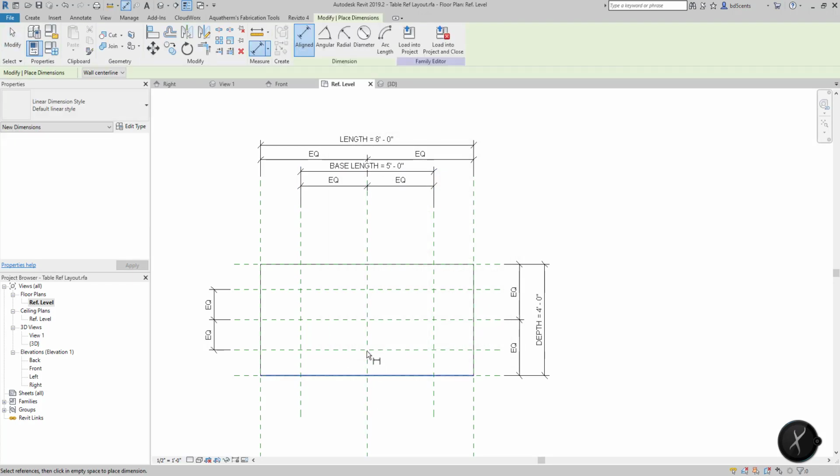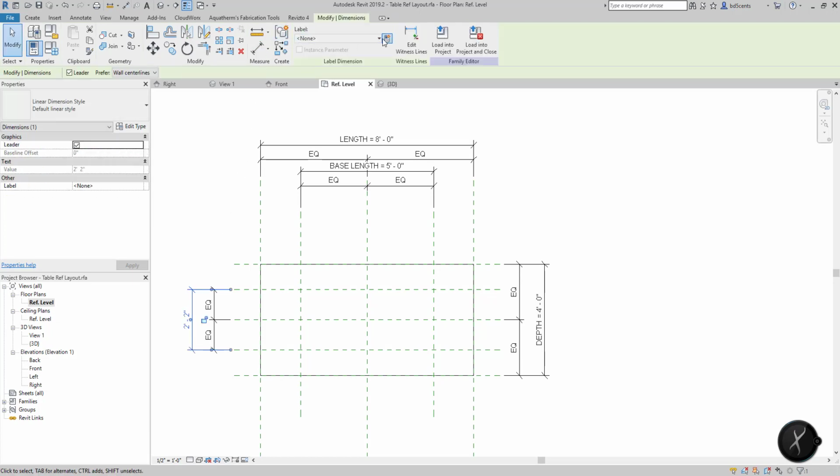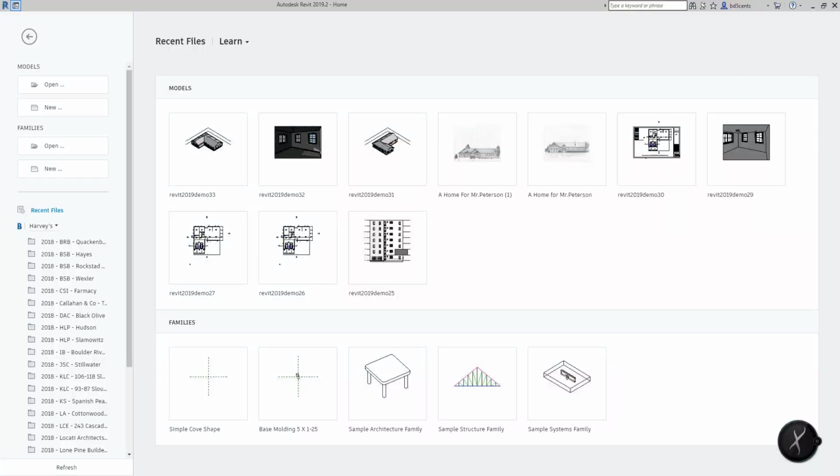DI from top to bottom, associative, and then I want to change that value to be base depth. Could be base width as well. In fact, I'd prefer that it's width, but since the handout says depth, we'll leave it as depth for now. So we'll hit OK. And now everything's structured based on those parameters, which means those parameters show up within the library, which means I can then start to associate types, which will flex this family to function in the base value of how this type functions. So it becomes very, very parametric.